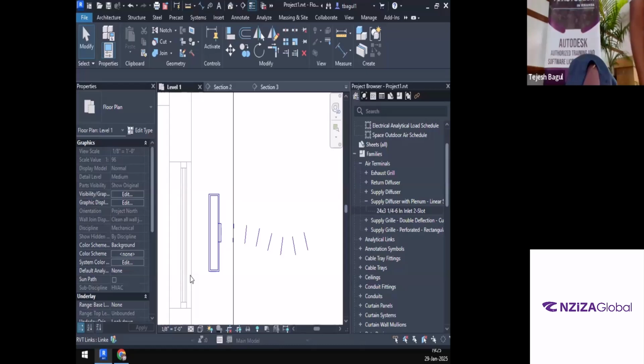What is the pressure rule for the expansion? Not the expansion. In general itself, it can be tilted, right? So think about it. You have a garden hose and you bend it. The water on the other side will struggle to come out. Same thing, we don't know how they are going to install this. It is going to be in the ceiling. It's not going to be visible. In that case, how do we confirm that the pressure drop is at the minimum? Make sense?